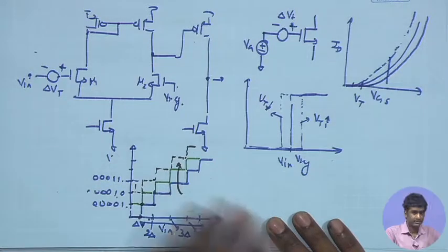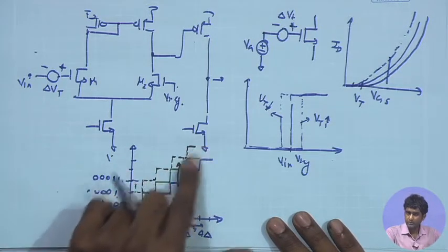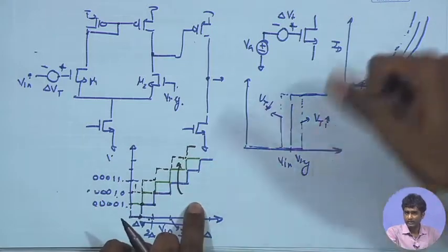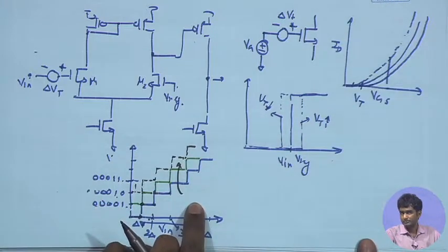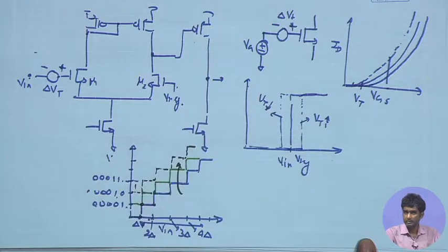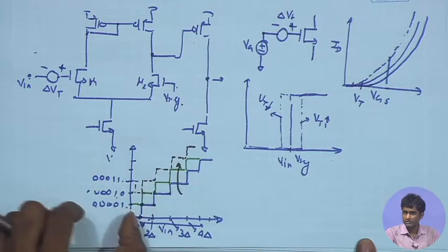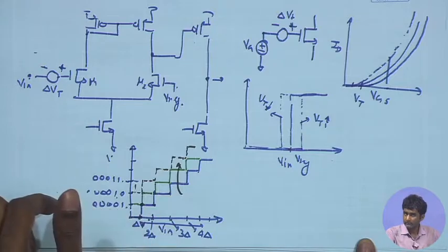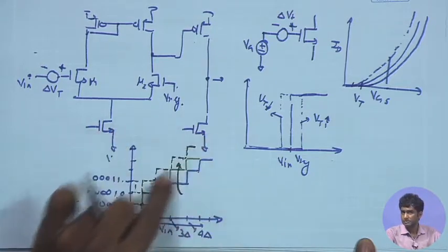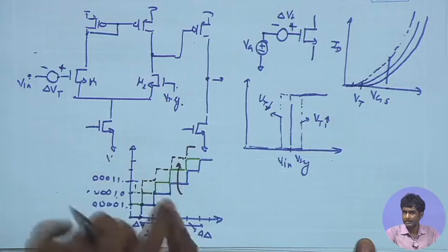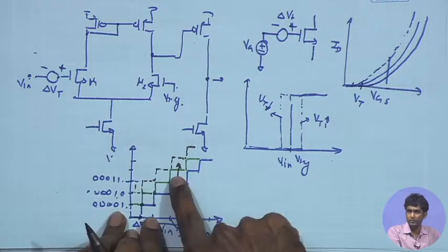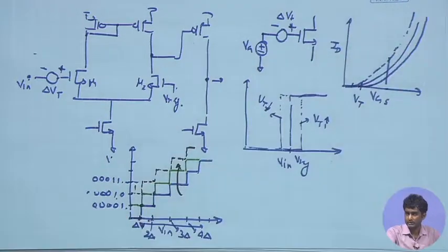So, we can test the ADC and we can find out what is the overall shift, and in the digital domain we can subtract that shift, and we can still retrieve the required value, at least for the range which is getting captured. The lower 2 delta which is getting missed, that we cannot capture, but the remaining can be obtained by just subtracting that 2 delta digitally. If you have the digital word, you can subtract it always if you know that this is offset. This is clear?